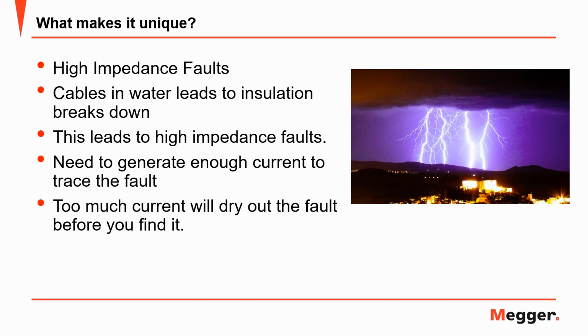When cables sit in water, their insulation breaks down over time. This leads to high impedance faults. The problem with trying to locate them is you need to generate enough current to be able to trace the signal. However, the more current you use, the more heat you generate. This will dry out the fault before you find it.